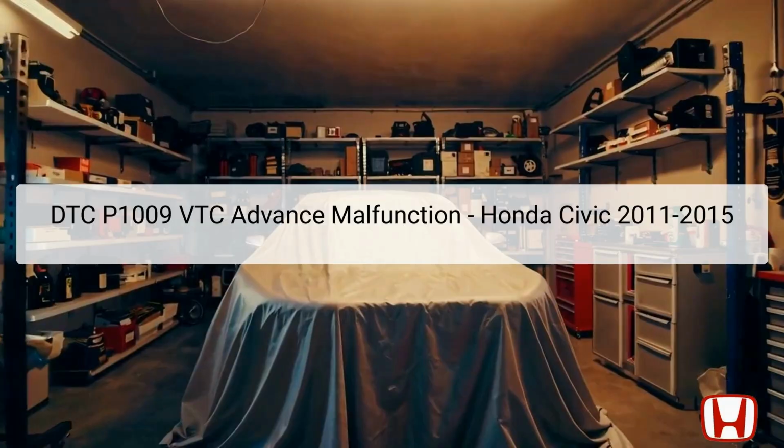The Diagnostic Trouble Code, DTC P1009, relates to a malfunction in the Variable Timing Control, VTC, system, which is crucial for optimizing engine performance and efficiency. The VTC system adjusts the timing of the intake camshaft according to engine demands, allowing for improved torque at low RPMs and enhanced power at high RPMs.